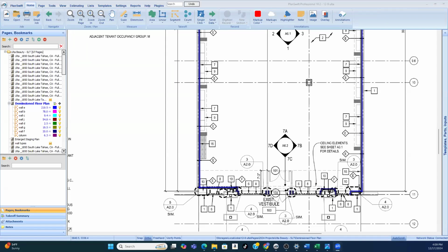The architectural set is basic. If you had to think about it anyway, it's everything that goes in and on the building, closes in the building once the box has been constructed. And so what's the box? Basically, the box is the structural set. Structural set is the foundation, columns, beams, headers, and your roof frame. That's the structural set. So that's the box. Simple as that. And shear walls. So that's the box.